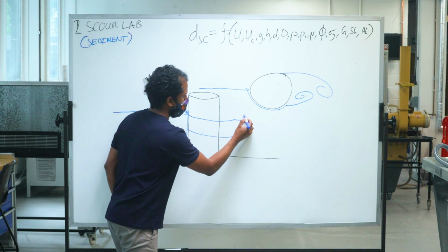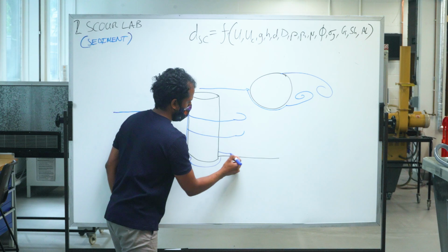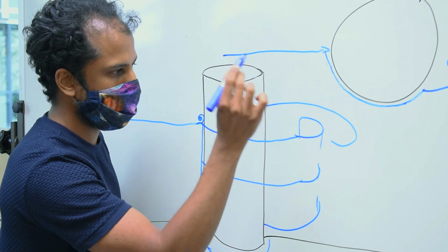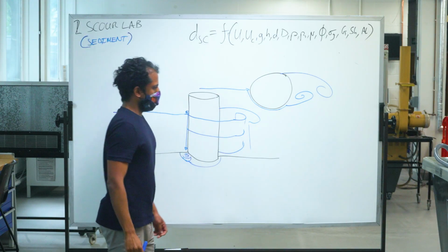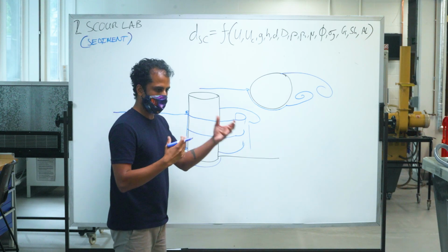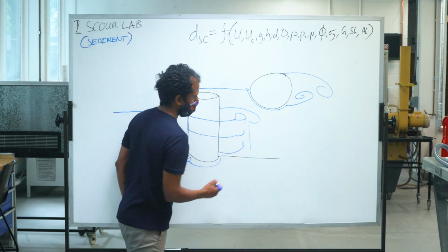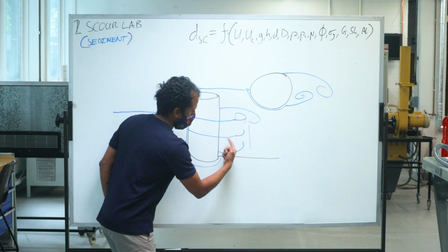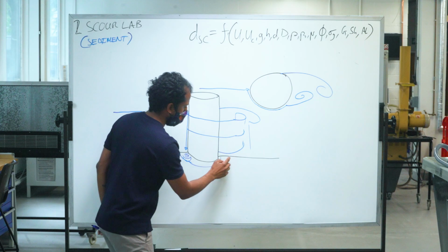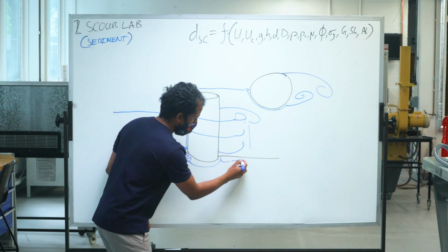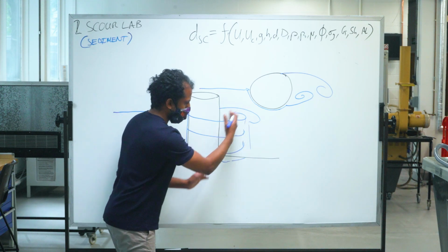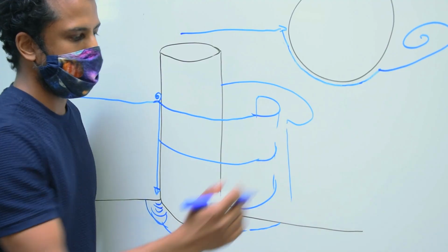We're getting these large counter-rotating vortex formations. And there'll be one on the other side as well. Over time, one will form on one side, one will form on the other side, and they'll slowly peel off downstream. Now, these are rotating like this, so they're actually sucking the water up. It's a little bit like a mini tornado. And therefore, with this mobile bed, you get some of the bed sucked up, and all this sediment is transported into this wake, and therefore taken downstream.